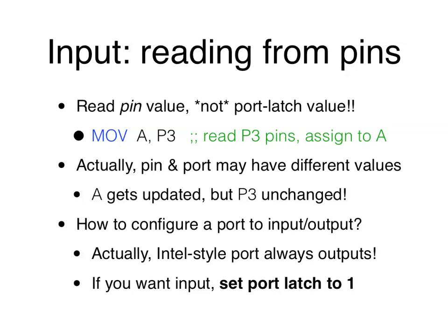Because at the very beginning, I said there's the concept of pins and the concept of port. By port, I mean the port latch or registers, which is a software concept, whereas pins are a hardware concept. Even though they're connected together, you may get different values. But instead of treating it as a bug, Intel makes it a feature. So how does that work? Well, it relies on that pull-up structure.